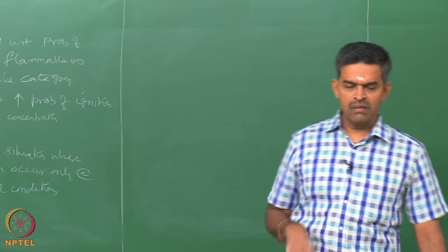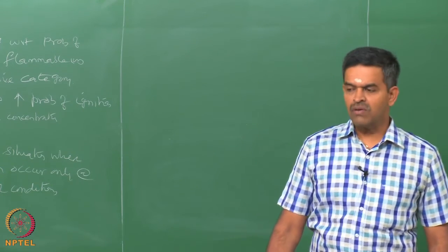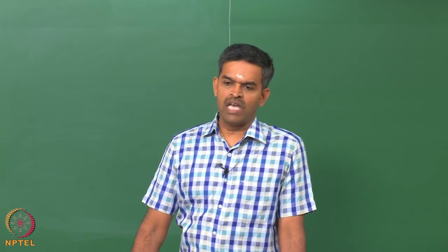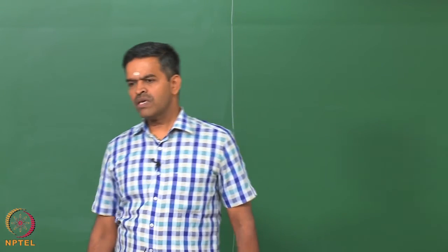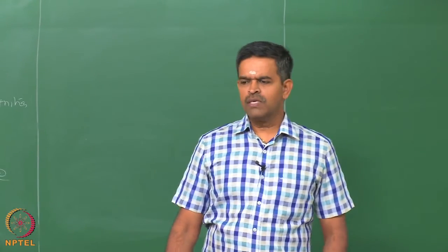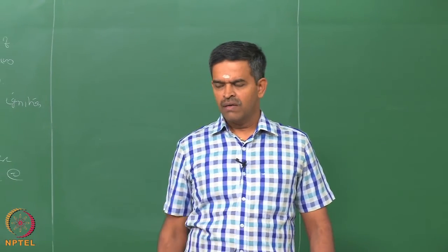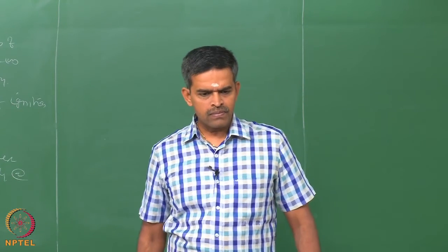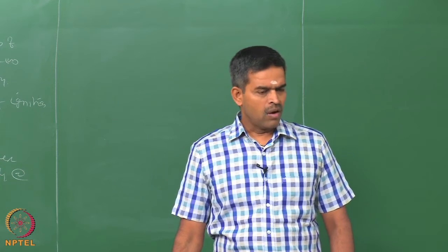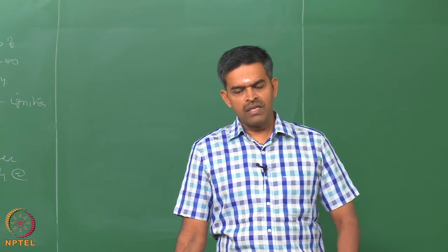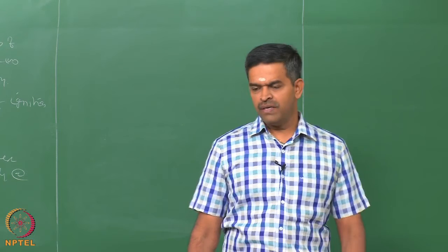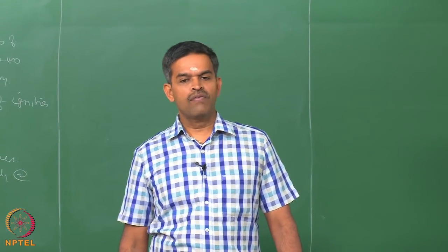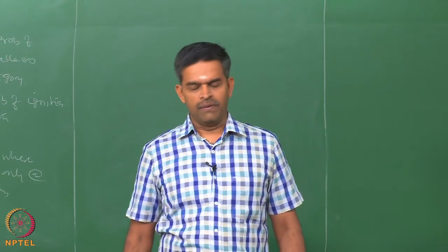One can also use impure nitrogen instead of pure nitrogen. When the vessel is not able to sustain the pressure or evacuation, one can go for sweep-through purging or siphon purging, which we discussed. One can also use flammability diagrams as an essential tool to decide when purging should be done. It means at what concentration of oxygen the nitrogen can be pumped in or purged out. So, whether you place the vessel in service or out of service can be decided so that the fuel mixture at any instant does not fall in the flammable region of that particular figure.